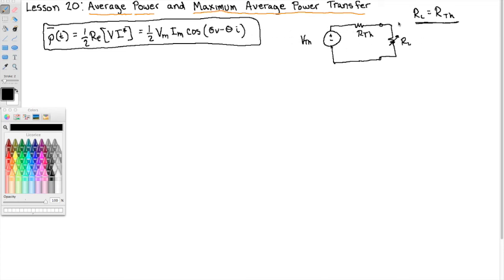So we're going to do the same thing with AC circuits, and whatever result we end up with, if we move to the specific case where the Thevenin impedance is purely real, then it has to reduce down to this. So that's a way of checking our result. Also, just to remind you that the maximum power that we got was V Thevenin squared over 4 times the Thevenin resistance. This is the maximum amount of power that a circuit can supply, or equivalently that a load resistor can draw from the circuit.